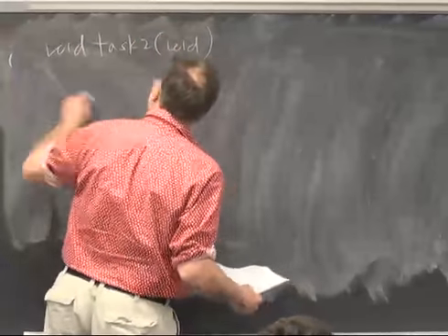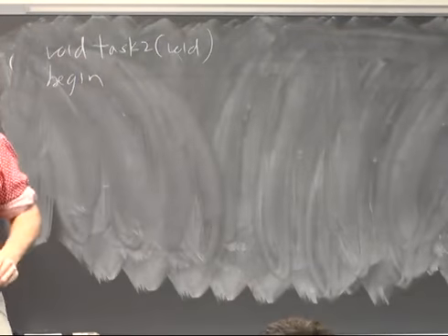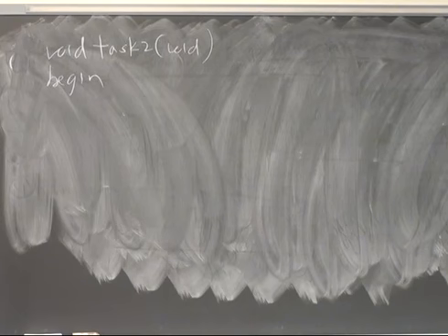So now we have task 2, and you remember task 2 is just ticking along, flashing an LED once per second, but because I'm using byte variables, I had to do a count to get to the appropriate number of milliseconds.